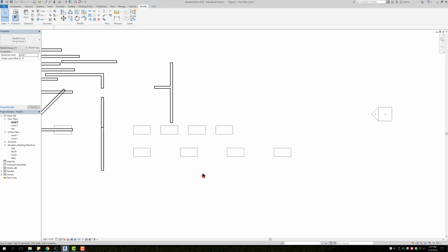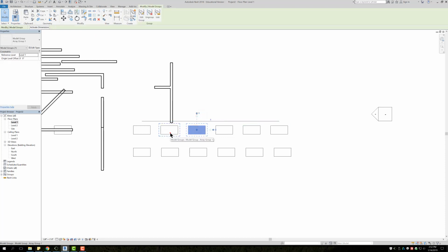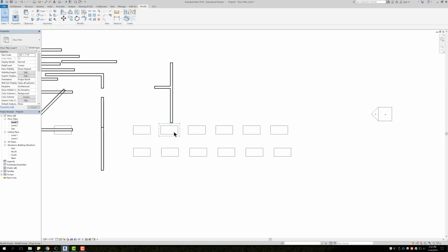One nice thing about linear arrays is if you select it, you can see here it brings up the number. You can go ahead and change that. So let's say maybe you wanted 6. Now it adds 6. If you choose this one and change it to 6, it doesn't expand the distance. When you're doing an array with second, you determine the distance between A and B, and if you change that number, it's going to keep adding on. If you do the option that said last and you determine point A and then the very last point B, it's only going to fill in that space.